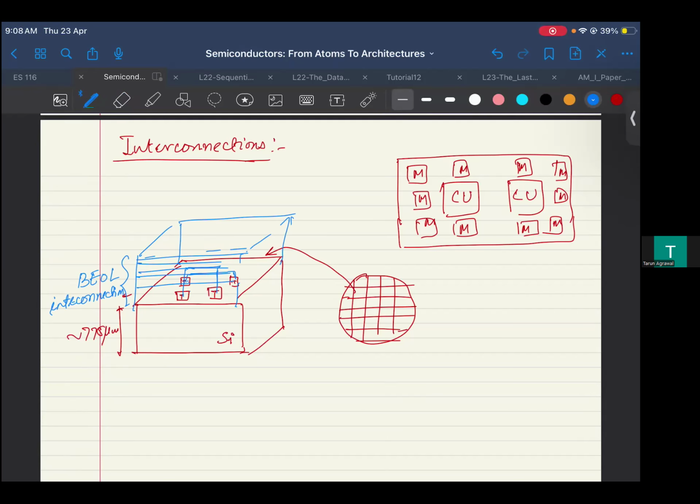And that depends on, as we discussed, this is a problem in computer science known as routing, or in physical layout called routing, and you have to figure out where you have less congestion, like the same thing your Google Maps does, right? Where do you have less congestion? Where will you have less fuel burning? All those things, which are the distance and everything, it would check, right? Depending on that, it would give you the right way of connecting these through multiple layers.